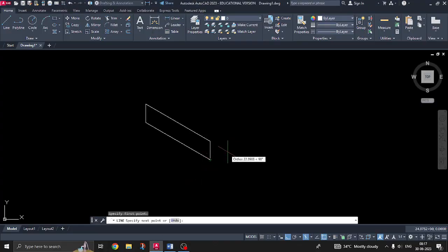We need this direction, so that you switch on ISO plane. When I am saying ISO plane, I am pressing F5. That is the meaning. Okay, in keyboard shortcut is F5, ISO plane. Then your cursor can be moved in this direction to draw lines. Okay, let us draw 25 mm. Okay, above, if you want above, switch on ISO plane. Okay, then 25 and complete. Enter. Again enter will take the line command.